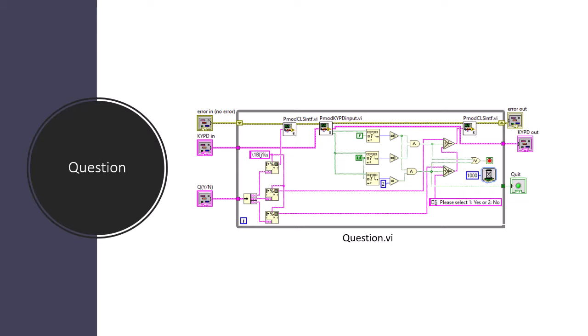For the row array, only a false in element 0 is accepted. From the column array, a true is accepted from either element 0 or 2. These results correspond to a key press of 1 or 2. When an accepted key press is detected, the loop is stopped and the appropriate response is displayed according to the question input cluster. Otherwise, the loop repeats.